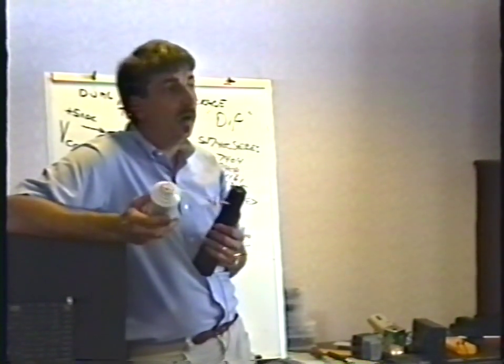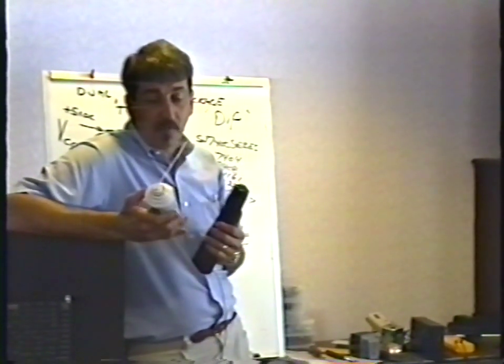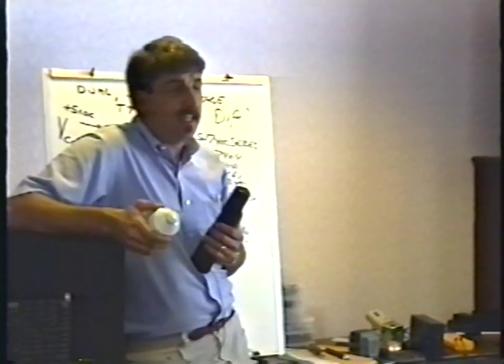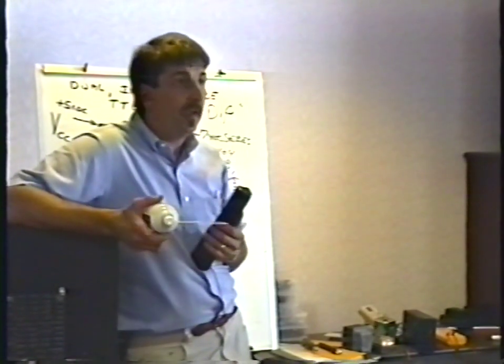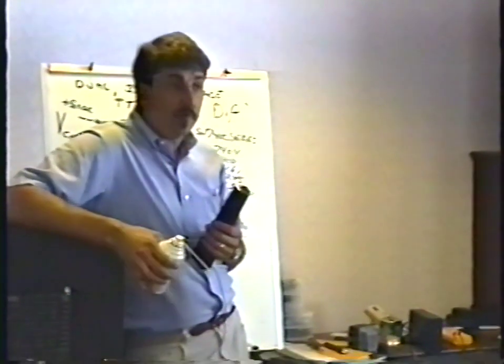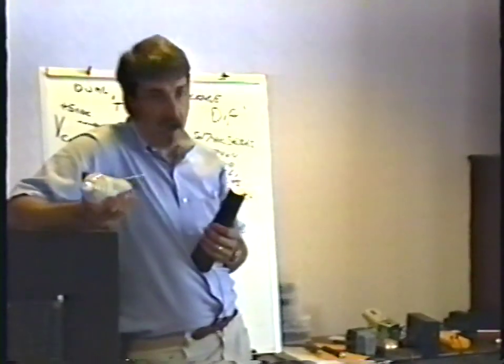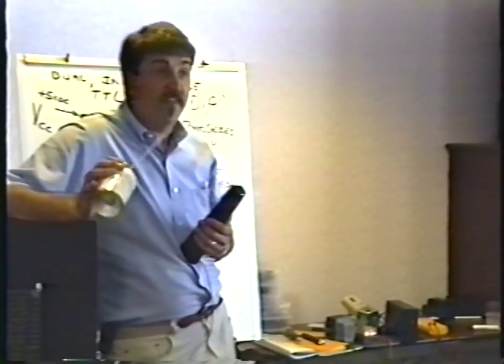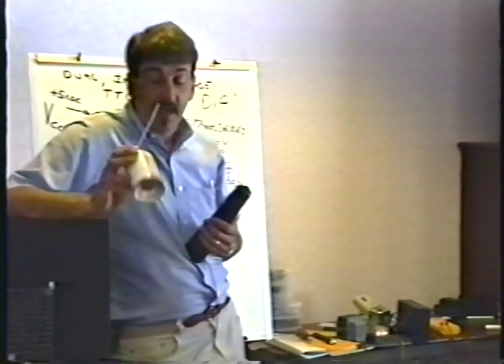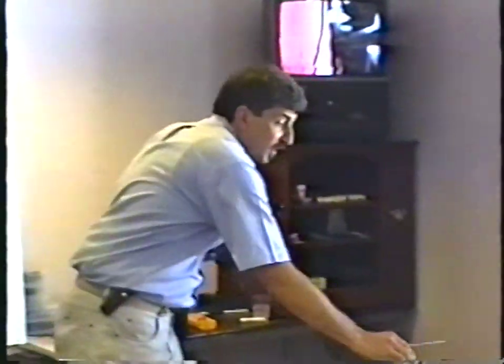You can get it at any electronics store. And it works great, not only for things like this, but in a monitor if you have a thermally intermittent problem, and anything that works when it's cold but fails when it gets hot can be found by freezing it. So that's a really cool method that works great, and I've fixed tons and tons of boards this way. Like I said, I've never failed to fix a thermally intermittent problem with freeze mist. Always been able to find it.